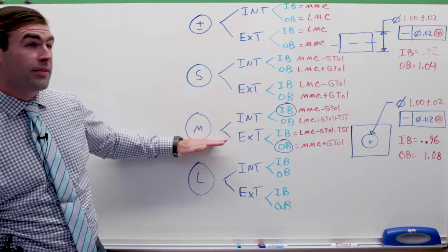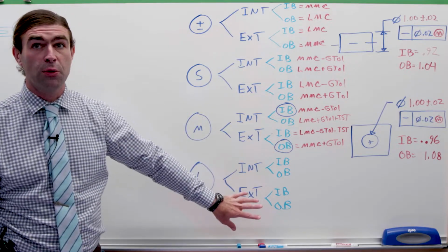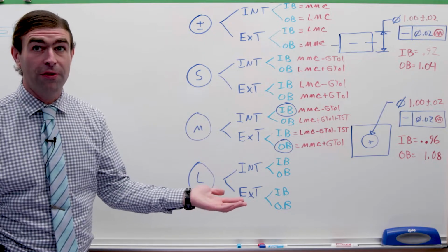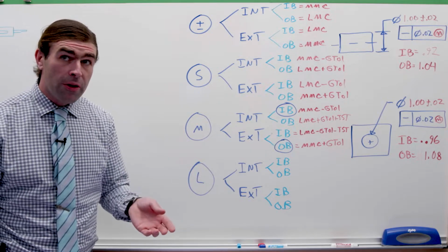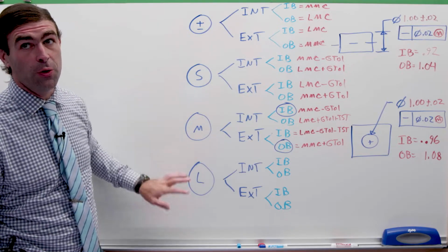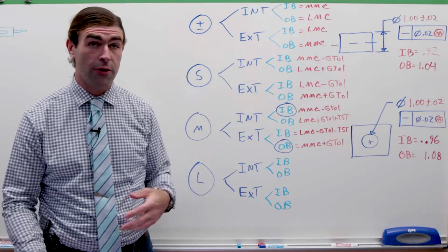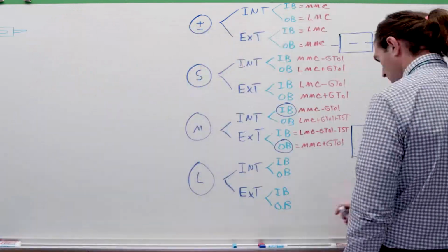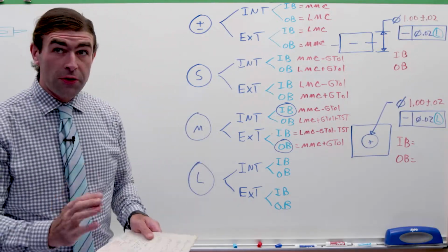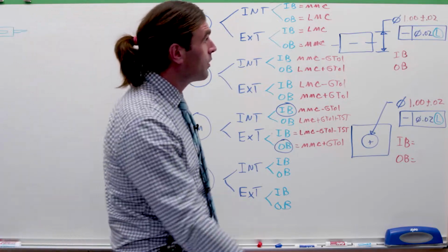Now, normally this is where you could stop in a typical design because LMC doesn't get used that often, but I'll go through it anyway. LMC is just going to reverse all of the MMC stuff. So if you're learning this for the first time, you might just want to focus on these first few and skip LMC because it can get confusing because you're reversing things. So let's jump into features modified at LMC.